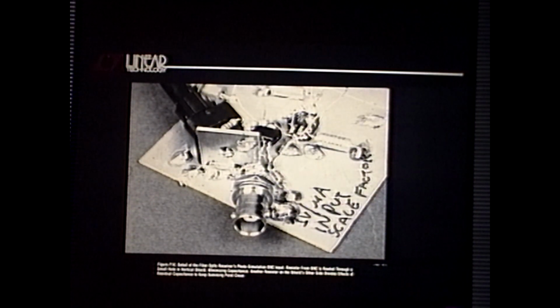So what I'm trying to do here is break up any RF transmission from the input of this thing into the summing point with shielding, and then whatever shunt capacitance there is across these resistors, I'm going to divide it away times the number of resistors. Is there a penalty there? Yeah, there's a penalty, which is to say, when you go from one resistor to the next, any capacitance from that point to ground looks like a lag. So at some point, the technique falls apart.